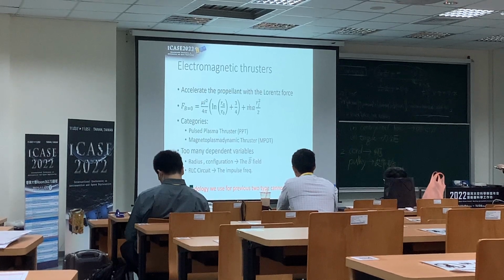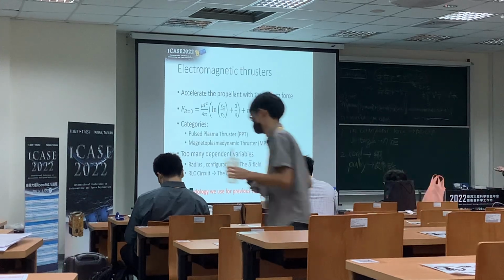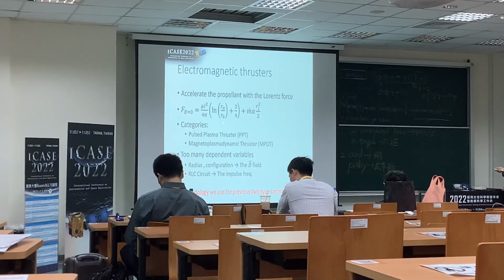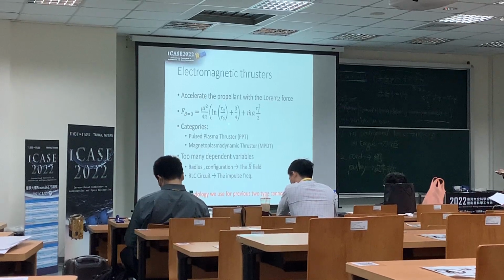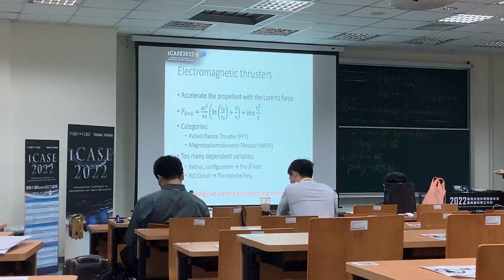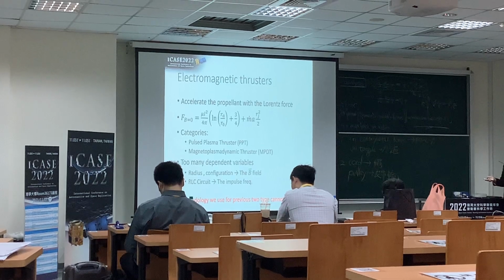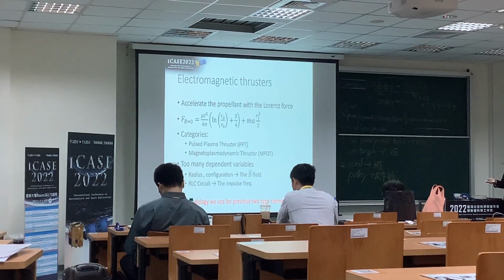Inside the thruster, the magnetic field controls the plasma, making the plasma particles circle in the thruster, and then the swirling energy is converted into axial energy and expels the particles with the divergent magnetic field.